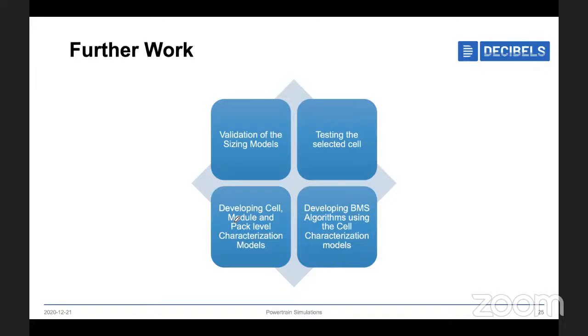So one thing is validation of your sizing model. In order to validate your sizing model, you have to develop a well-to-wheel analysis model. Up to now we are giving the input as a drive cycle, and we are getting motor size, battery size, transmission, gear ratio, energy consumption, and all the stuff. But now we'll give the battery pack size and the motor parameters, and we'll give the drive cycle, and we'll ask the driver to accurately follow that drive cycle.